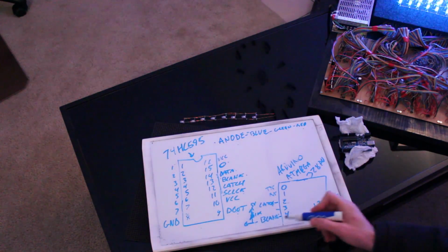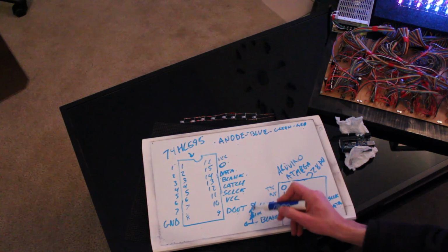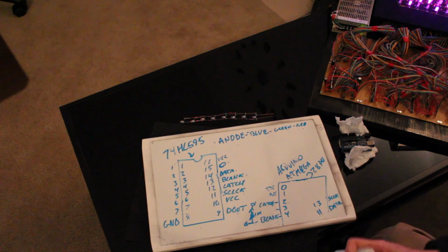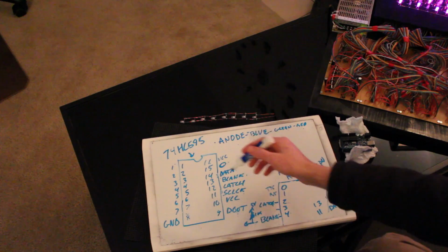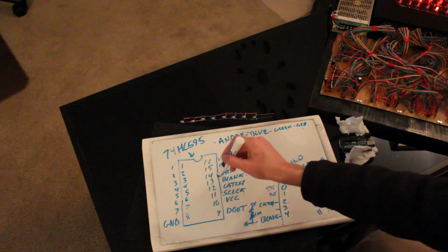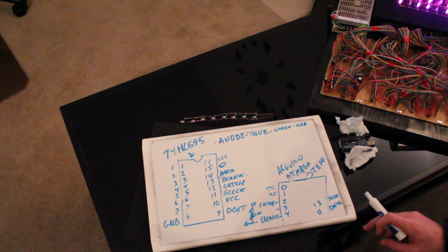That's off Arduino pin 4. And you'll notice I have a 1K pull-up to 5 volts off that. That's just so during boot up, when we're not sure what we're setting all these pins to, the pins all default to an off state. And that goes to the blank pin across all 25 shift registers.